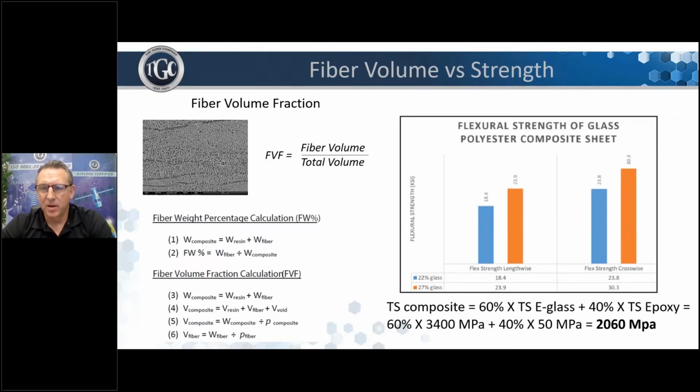Once fiber volume gets to a point where resin can't wet out the fiber, composite properties will start to go down. And they go down quickly because flaws are introduced into the composite. That threshold may vary by process and fiber type. Typically, 60 to 75% fiber volume is an area where the upper threshold of fiber volume is found.